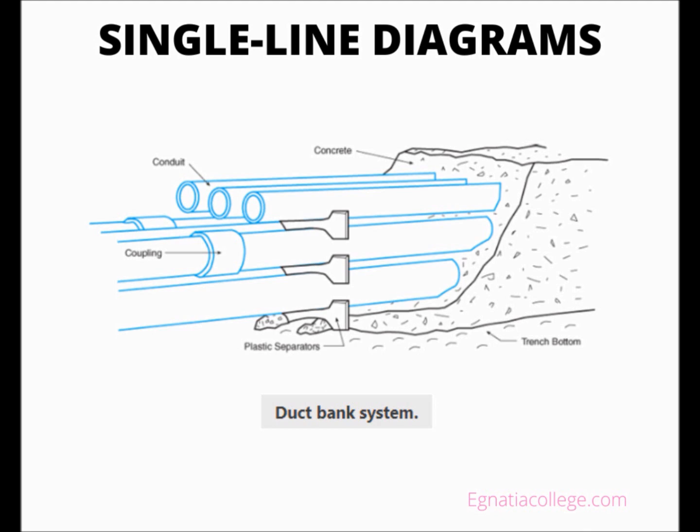To comply with the National Electrical Code, the service entrance section may have up to, but must not exceed, 6 main disconnecting units, switches or circuit breakers. Four main fused switches are shown in the existing portion of the single-line drawing. Note that this single-line drawing shows only a portion of the complete existing service entrance section. The service entrance section indicates that it is located outside by the NEMA 3R enclosure.